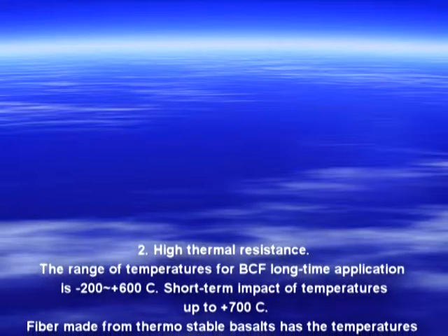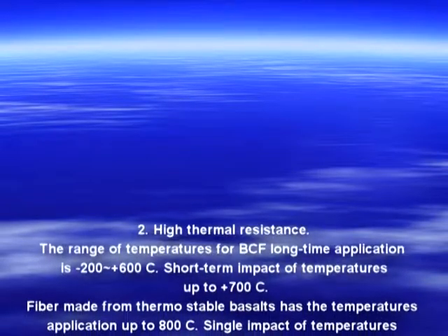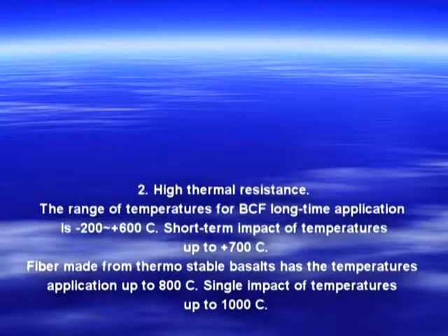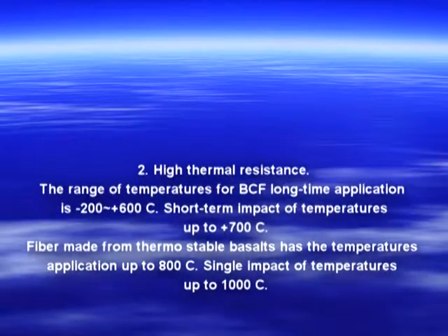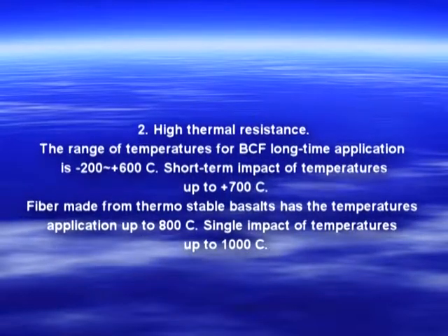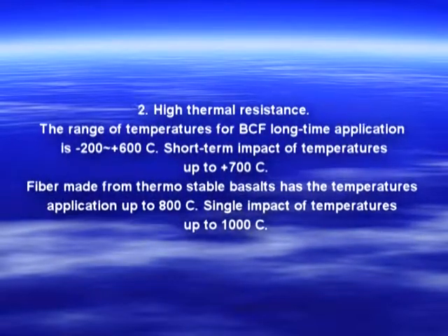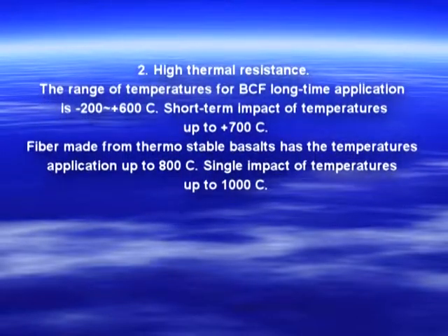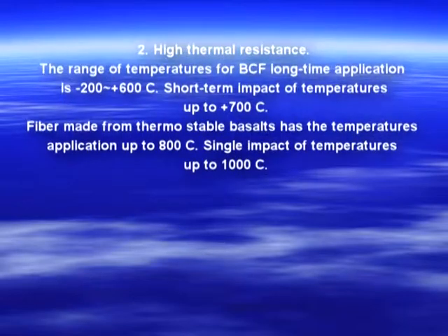The range of temperatures for BCF long-time application is -200 to +600 degrees Celsius. Short-term impact of temperatures up to 700 degrees Celsius. Fiber made from thermostable basalts has temperature application up to 800 degrees Celsius. Single impact of temperatures up to 1000 degrees Celsius.